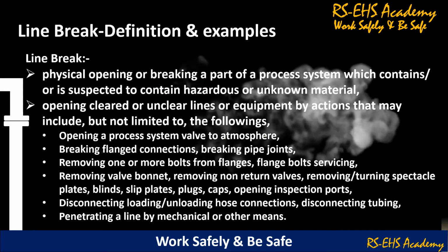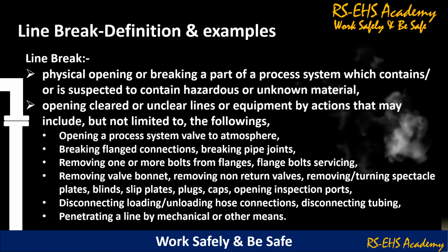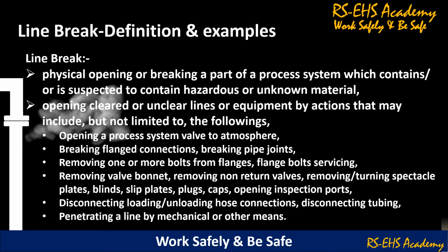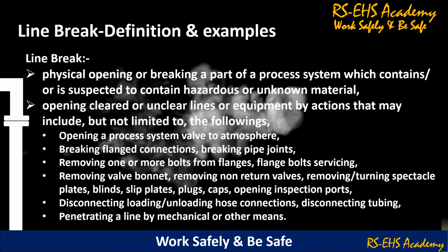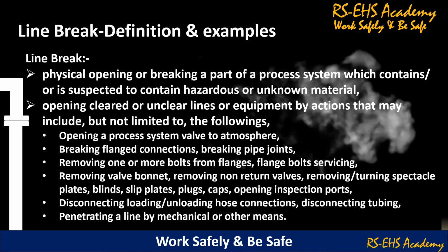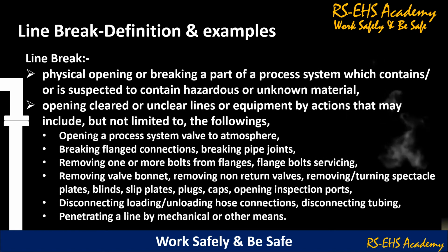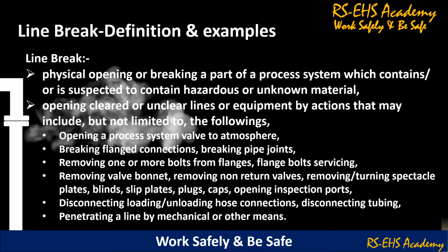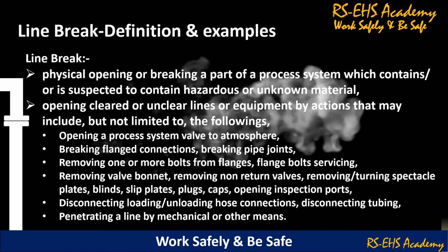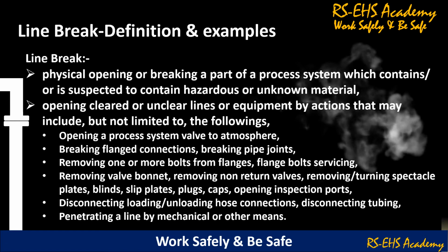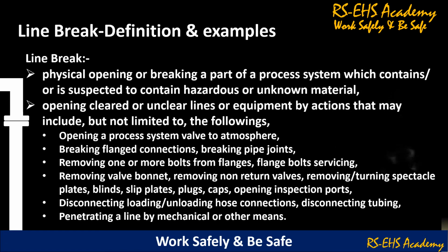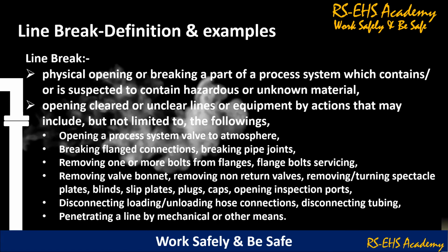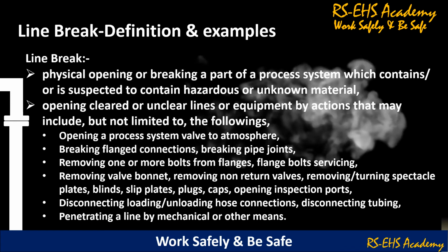Line break: physical opening or breaking a part of a process system which contains or is suspected to contain hazardous or unknown material. Opening cleared or unclear lines or equipment by action that may include, but is not limited to, the following: opening a process system valve to atmosphere, breaking flange connections, breaking pipe joints, removing one or more bolts from flanges,